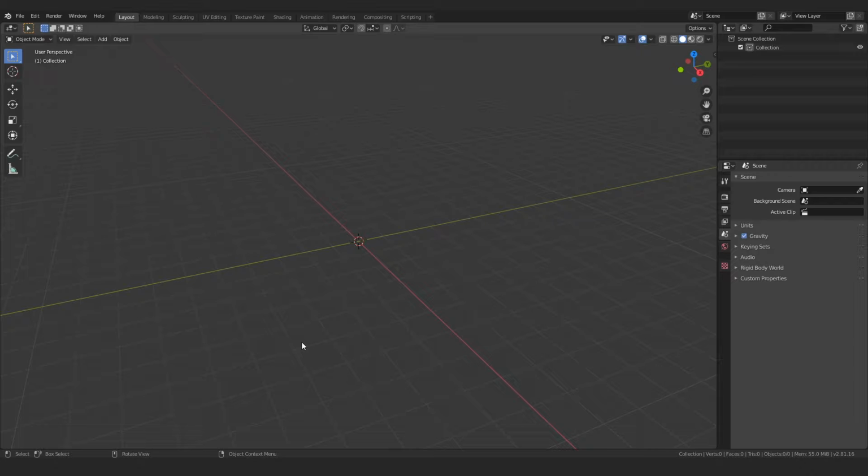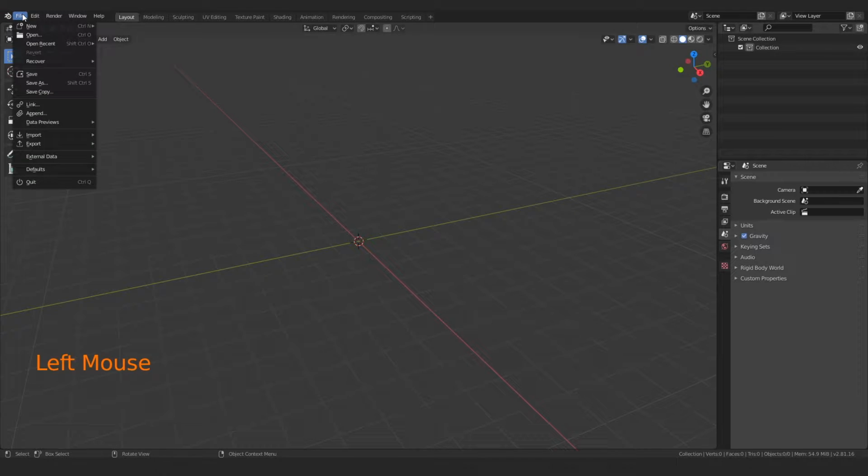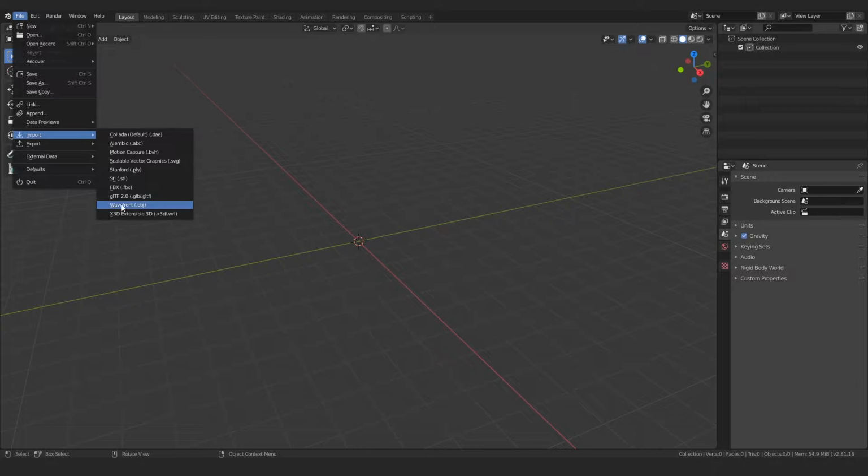If you're familiar with the Blender workflow or not, just get used to navigating these different windows and what they do, and you'll have your bearings in Blender in no time. All right, so with that out of the way, what we need to do now is get our photogrammetry mesh inside of Blender, finally, right? So we're going to go to the File menu, say File, Import, and choose the option which is Wavefront .obj.